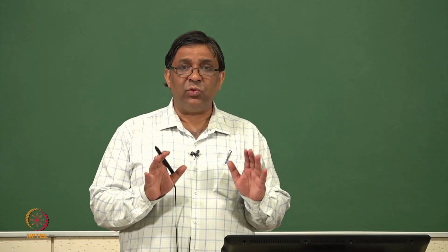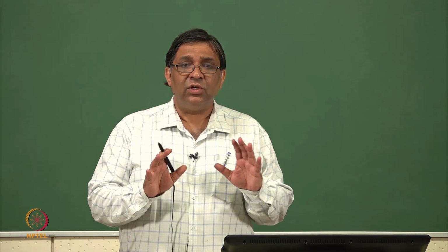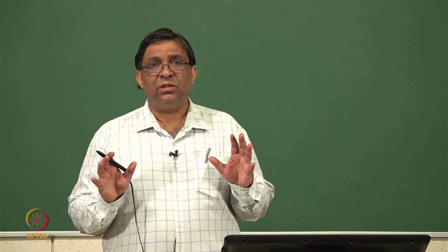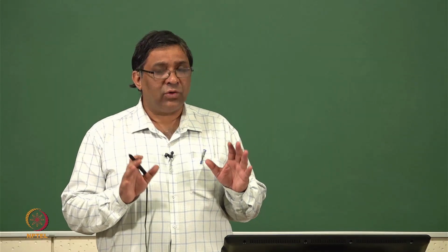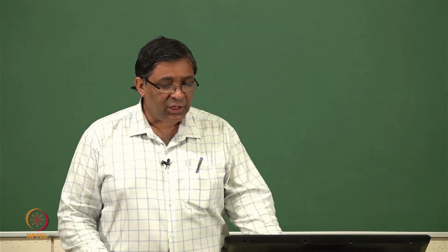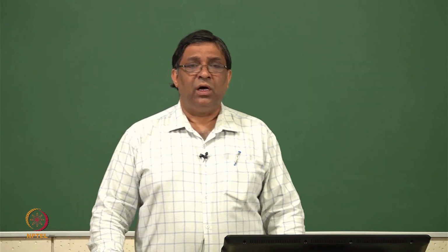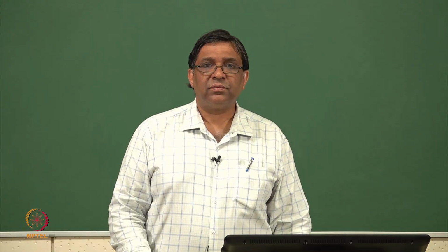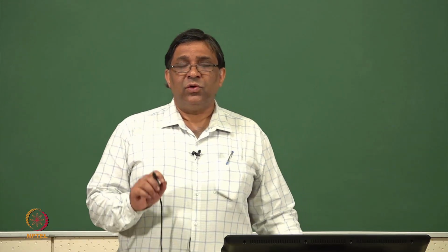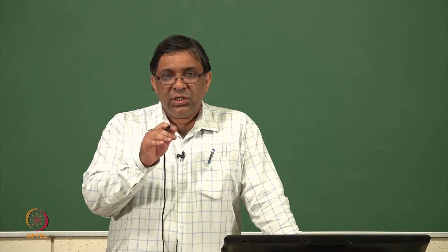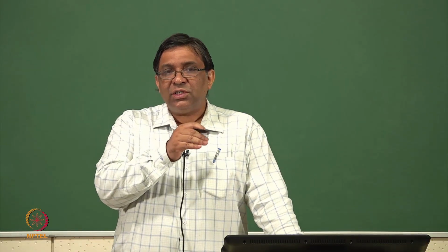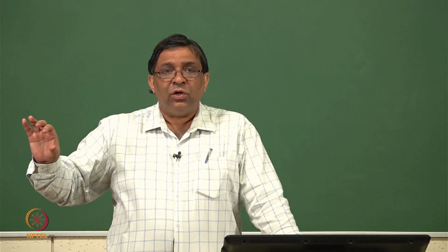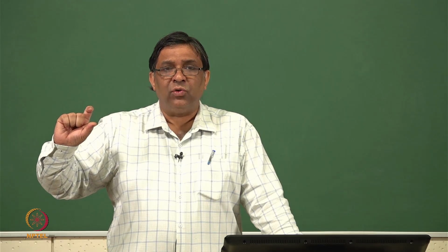Amorphous silicon is definitely one material which has initiated the research and technology in thin film solar cell. But I will come back to other thin film solar cells in my third lecture. But before that, let me introduce again the light trapping process. Just recollect it. I was discussing light trapping in crystalline silicon solar cell, which is a thick silicon wafer.